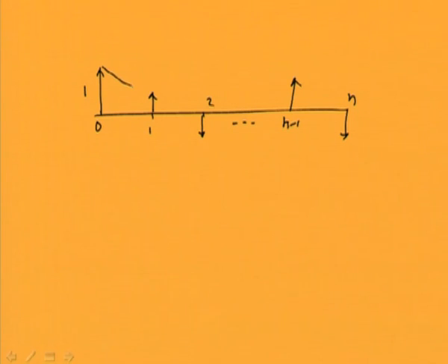Okay, so this is the mode shape for a multi-degree of freedom system. Mode shape is nothing but the relative displacements of the various disks. So you can see that once we obtain the displacement of the shaft at one end, using the transfer matrix we can transfer that information up to the other end. Okay, so this is corresponding to omega n1.